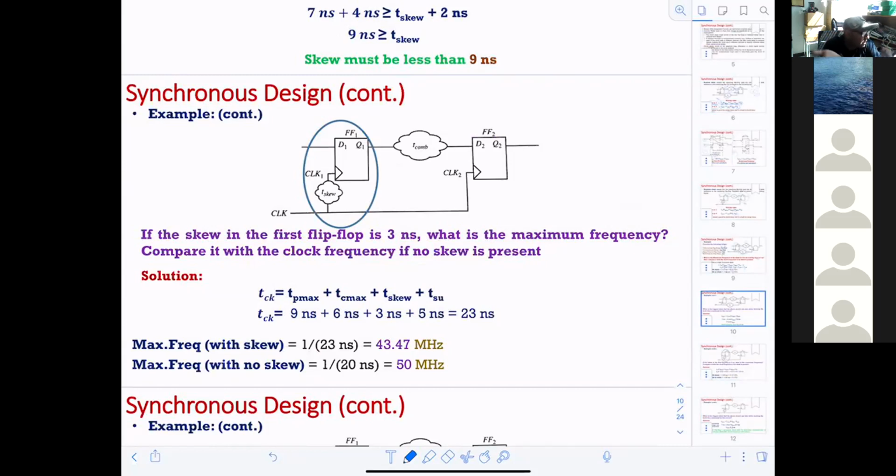Then you have to apply both and see what will happen, right? Instead of 2 stages like this, it can be 4 or 5 stages, right? And instead of both flip-flops having the same timing, they can have 2 different timings, like the TSU of flip-flop number 1 different from the TSU of the second one, and the T hold different from the second one. That makes sense?